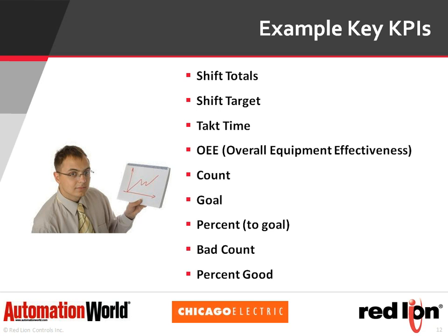Another very common metric that's displayed is OEE, or overall equipment effectiveness. What that simply is, is a measurement of resource utilization. It's a machine or a process's availability times its performance times its quality. And obviously you want that number to be as high as possible. Honda, for example, I'm told, targets around 85% OEE. World-class organizations would target around 80 to 85%.